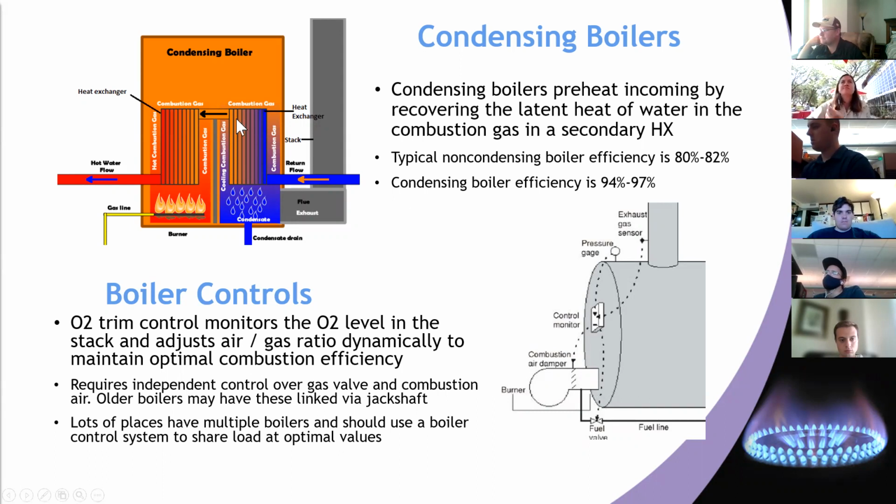Yeah. This second heat exchanger usually has to be made out of stainless steel because the condensate is caustic. So the extra expense of a condensing boiler is for a higher quality heat exchanger right there, and the extra engineering that goes into it.